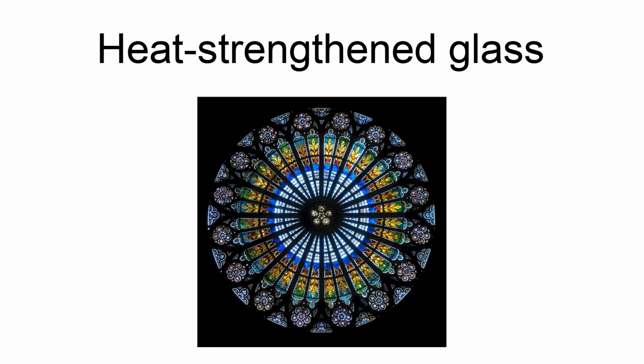Heat-strengthened glass is glass that has been heat-treated to induce surface compression, but not to the extent of causing it to dice on breaking in the manner of tempered glass. On breaking, heat-strengthened glass breaks into sharp pieces that are typically somewhat smaller than those found on breaking annealed glass, and is intermediate in strength between annealed and toughened glasses. Heat-strengthened glass can take a strong direct hit without shattering, but has a weak edge. By simply tapping the edge of heat-strengthened glass with a solid object, it is possible to shatter the entire sheet.